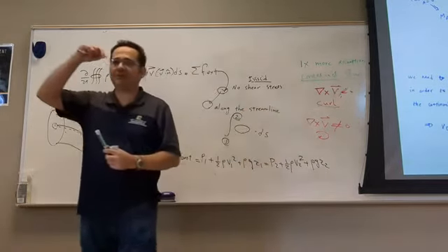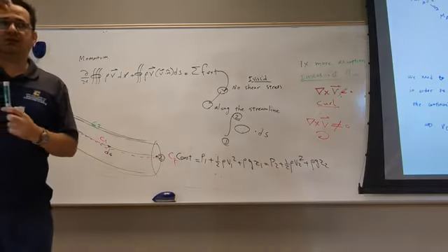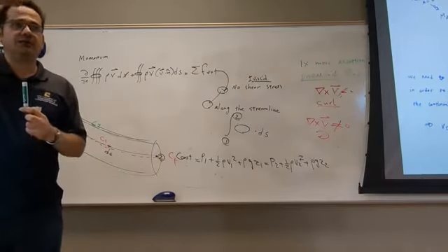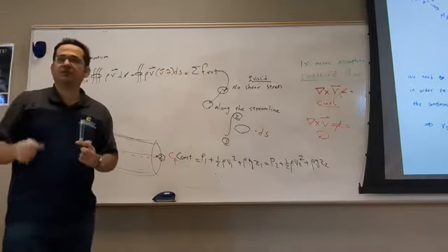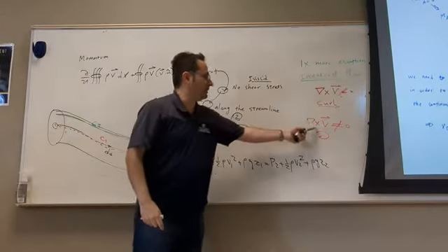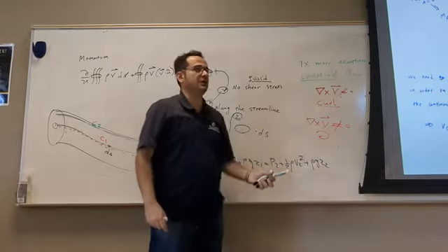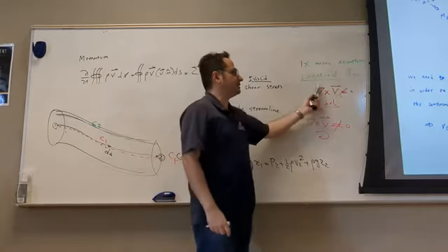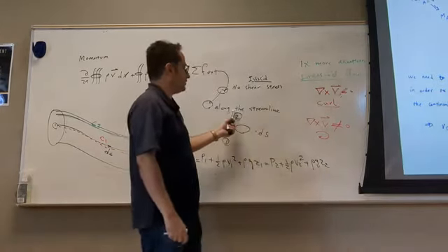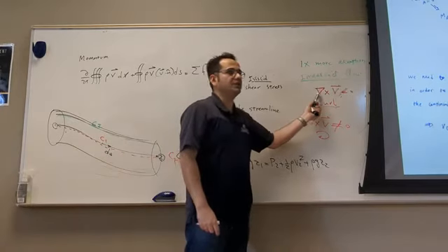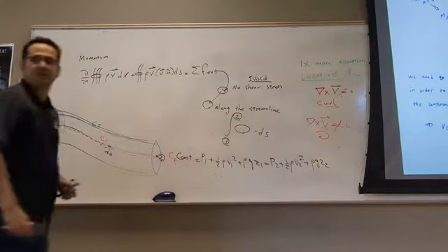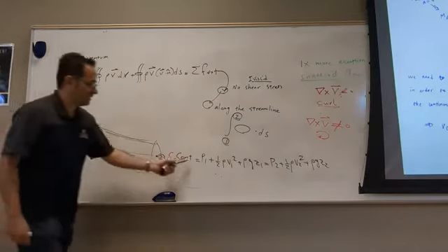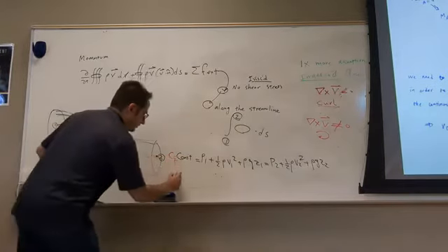Physically speaking, that means if you put a needle with an arrowhead on top of it anywhere in the flow, if your arrowhead is going to rotate, it's rotational. Otherwise, it's irrotational. Now you can show that later with the energy equation. If you make one more assumption that the flow is irrotational, then you can get this constant equal. So C1 is equal to C2.